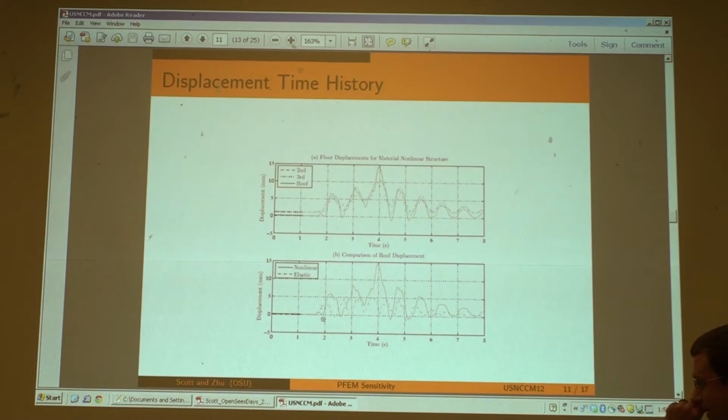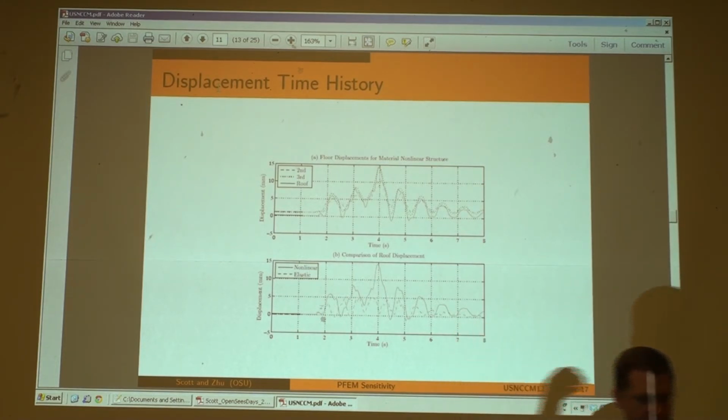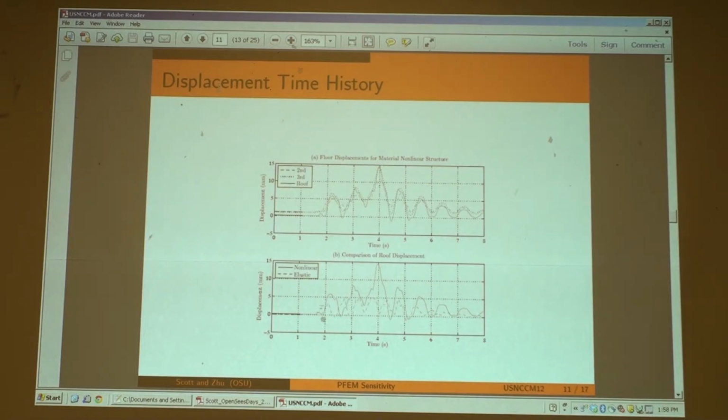But again, the point is, we can use our earthquake engineering models, fiber models, and do wave loading on those, and this could be the simulation framework for performance-based tsunami engineering, if you will. We could compute demand parameters based on different loading conditions.